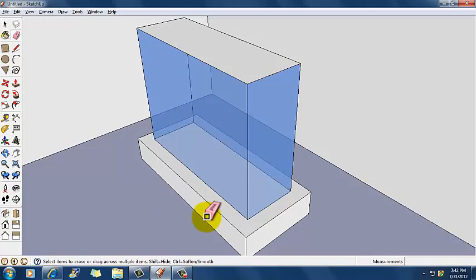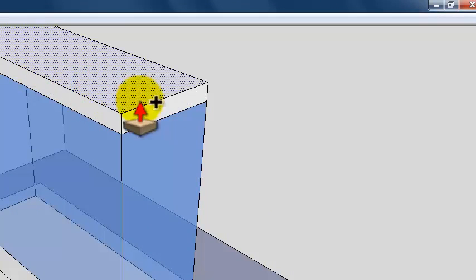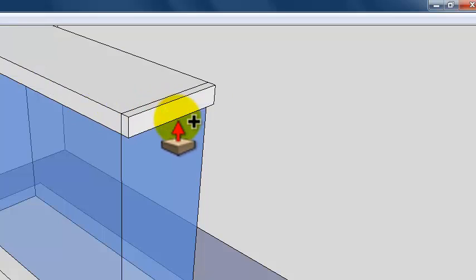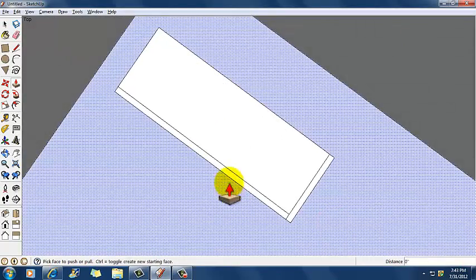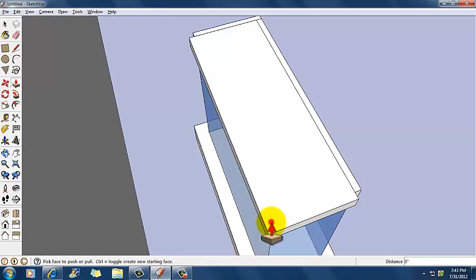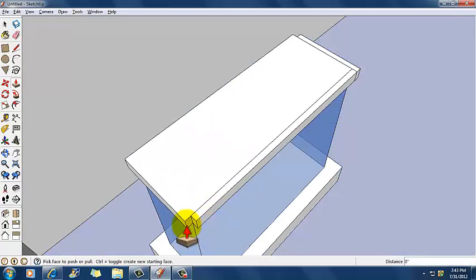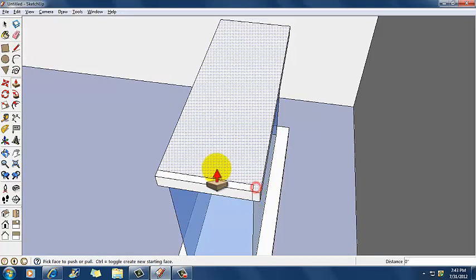And there we go. Maybe this top wants to have some thickness to it, so I do another push-pull, make a copy, pull that up 4 inches, and pull this out 2 inches, repeat. Ooh, flying around. Got some funkiness going on here. So I need to do some erasing. That's what happens when you have extra lines. Things get complicated sometimes. So push pull, bring that out.